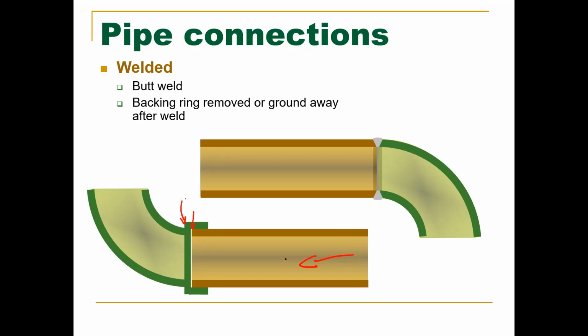All right. We wanted the conveyance of fluid. We don't want anything that's in here to come out of the pipe. So it's expansion. It's just that little bit of room for expansion. You put it all the way in, and then you just pull it out about a 1/16 of an inch. Nothing too great.